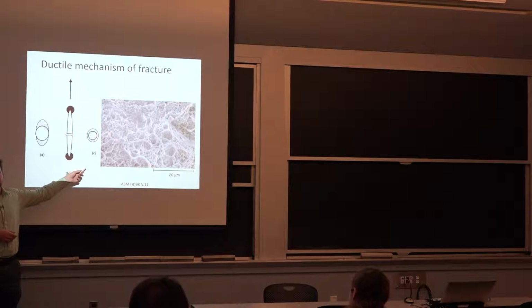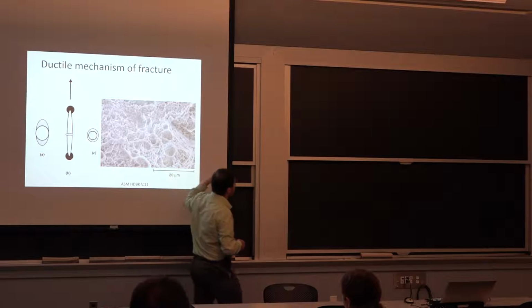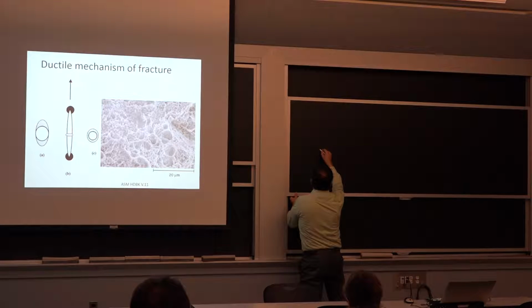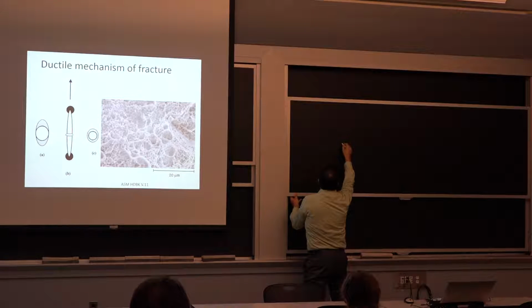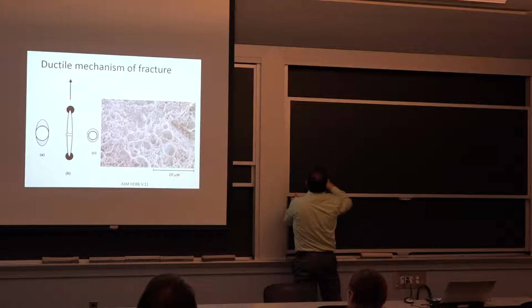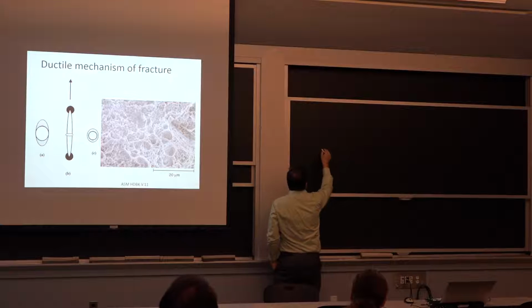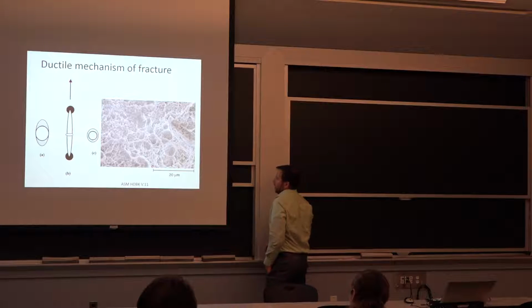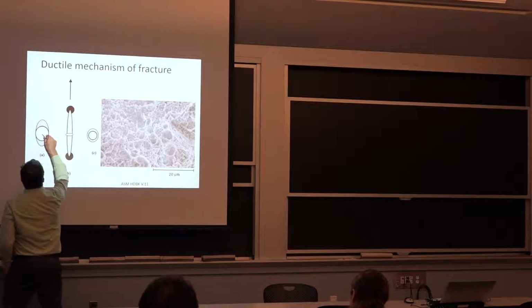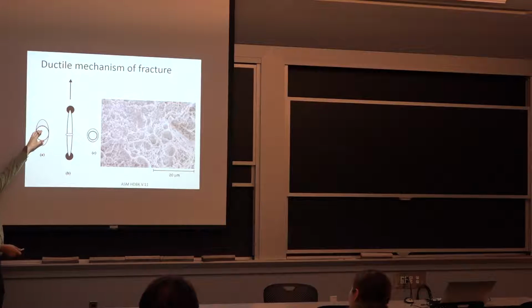what you'd like to have on the fracture surface, this is looking down on a crack that's separated, is a ductile mode, which is essentially a number of dimples. So if we were trying to do a profile of this surface here, it will pretty much look like this. It's just a little ligament. So essentially half holes into the material. There may be some bigger ones that are the origin of forming. Essentially, you had an initiation of a little void in one area. In this schematic, it started at an inclusion. So you have a hard piece of material in the material.